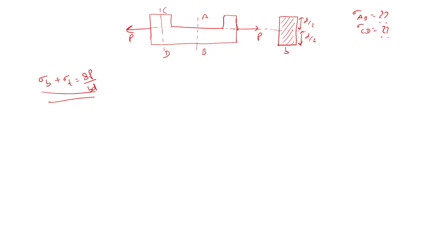So we can individually add the stress components, because both are normal stresses, right? Tensile stress and bending stresses both are normal stresses, and shear stress, like torsion, will come under shear stresses. So normal stresses we can add, because in bending, a variation happens across the section. Let's suppose this is the cross section, so in one direction it would be tensile and in the other direction compressive, and the magnitude would be the same. This would be the neutral axis line.